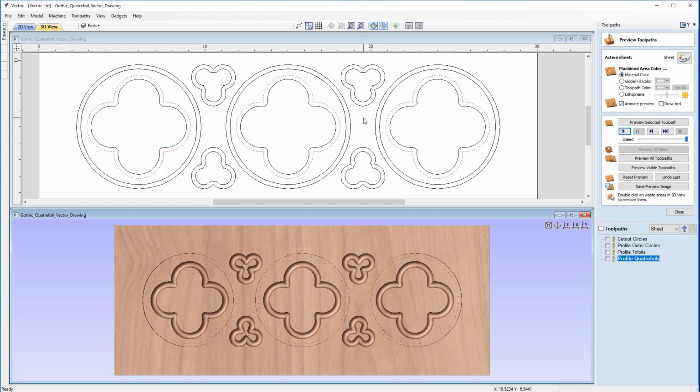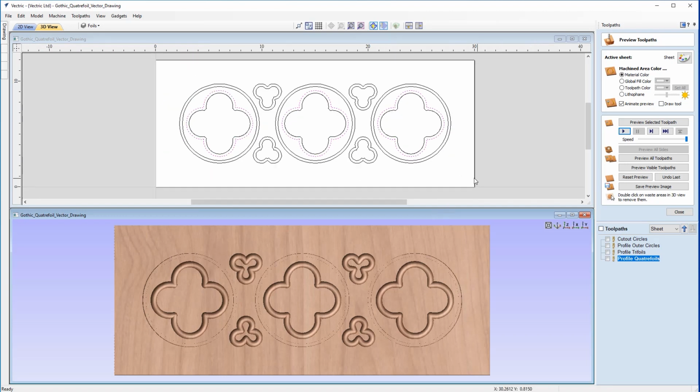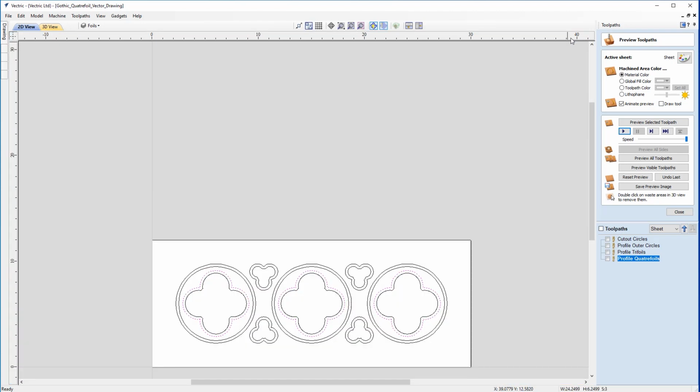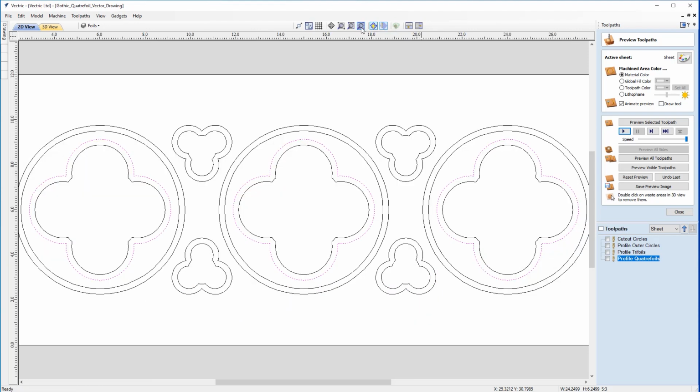That would be using the same tool again, the 1/2 inch ball nose, to create a nice scallop line across the bottom and top of the quatrefoil to match these that we've already created. So with that, I'm just going to maximise the 2D view, and we're just going to centre that by zoom active view to selected limits. And we're going to want to access the top and bottom groove vectors that we switched off earlier.